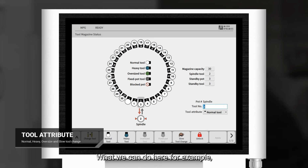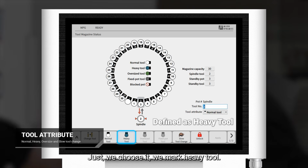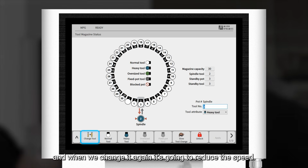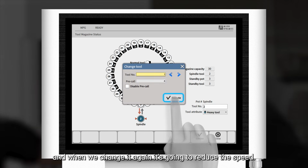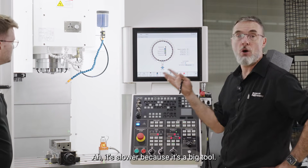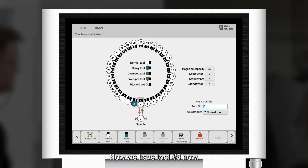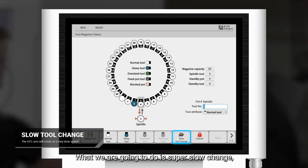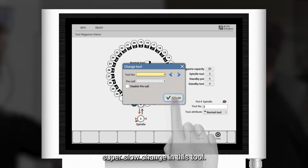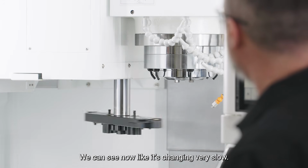What we can do here, for example, let's say this tool number 2 is a heavy tool. We just choose it, mark heavy tool, apply it, and when we change it again, it's going to reduce the speed. Let's call tool number 3. It's slower because it's a big tool. Now we have tool number 3. What we are going to do is a super slow change, like we have the turtle here. We can see now it's changing very slowly.